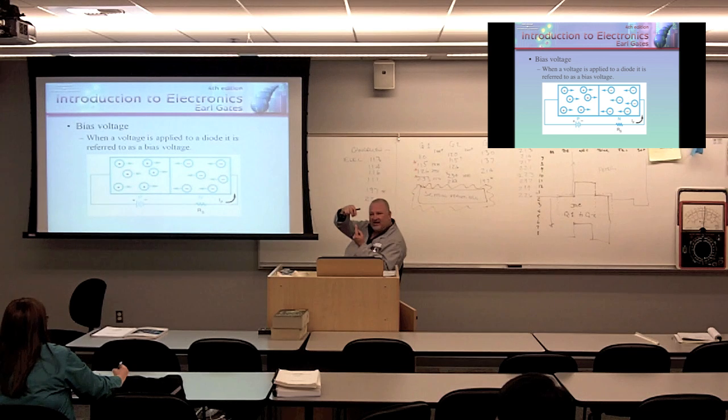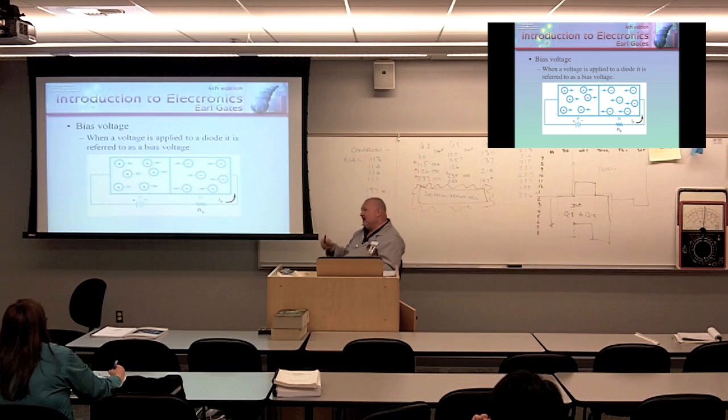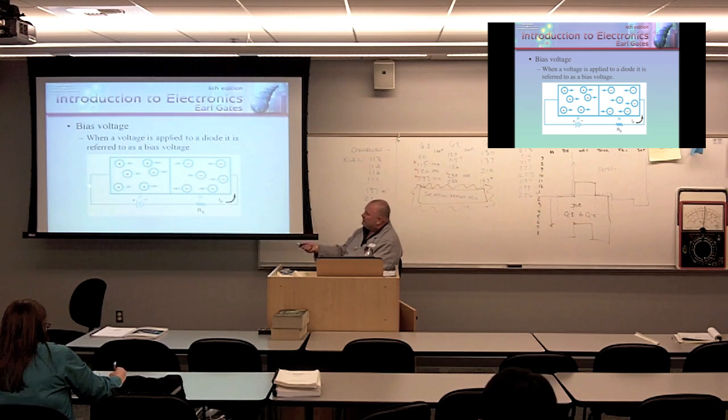But as soon as you suck on the straw, what's going to happen to the ball? It's going to seal it. So that will only allow the air to flow one way, but it won't be able to allow the air to flow the other way. It's what's commonly known as a check valve. A diode is the electrical equivalent of a check valve. It's going to allow current to flow in this direction and this direction only. So when we forward bias a diode, current flows through it.